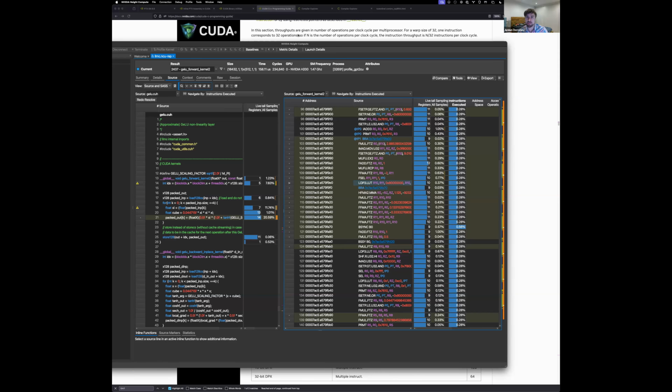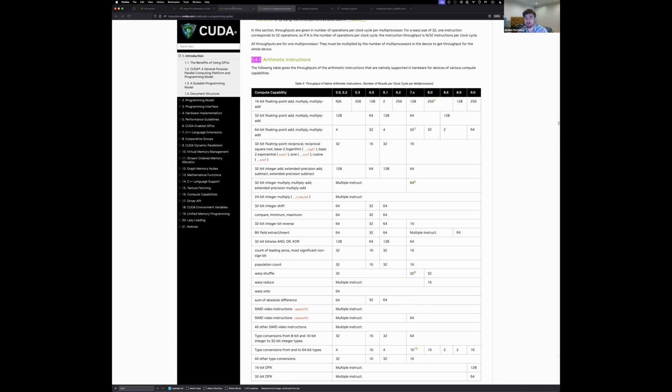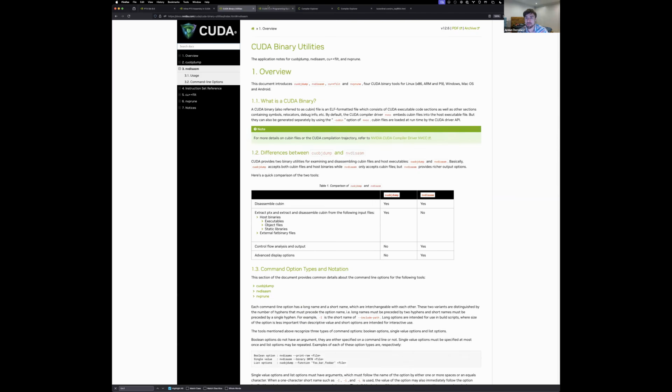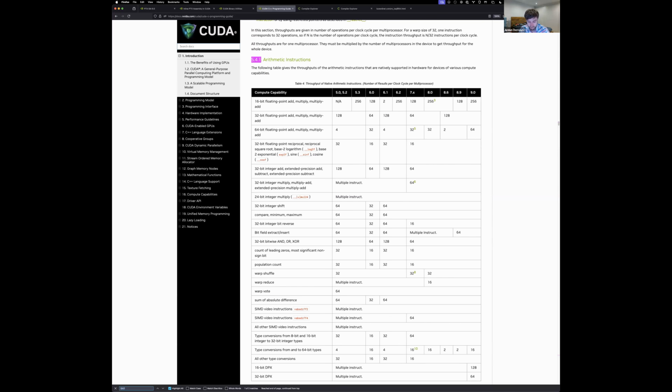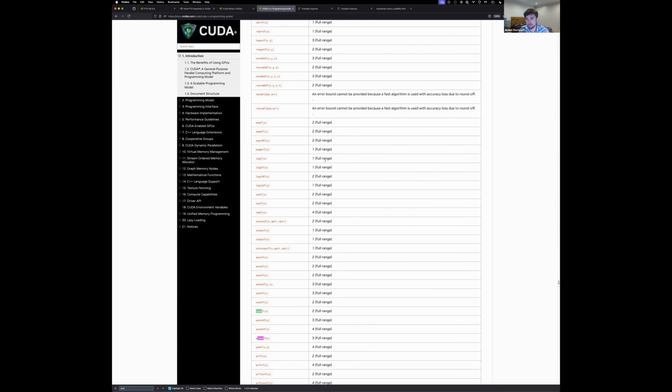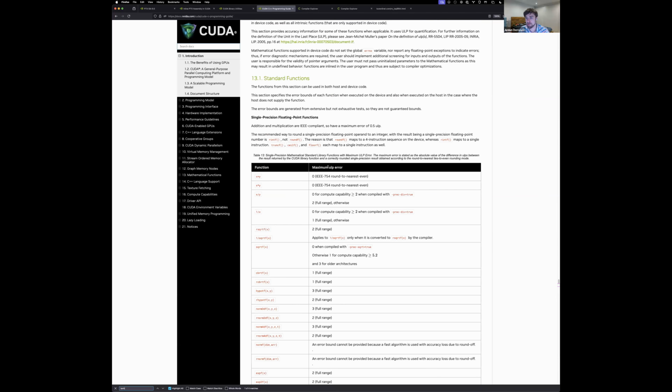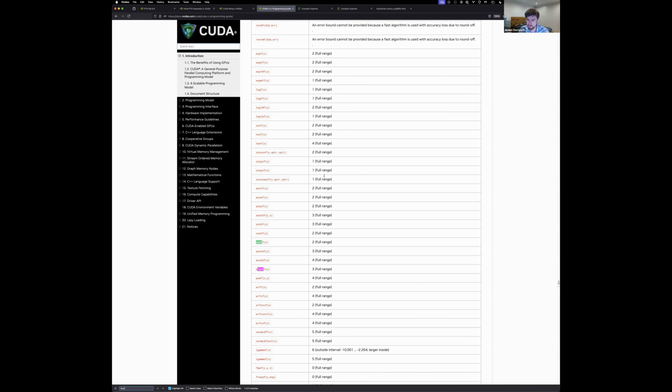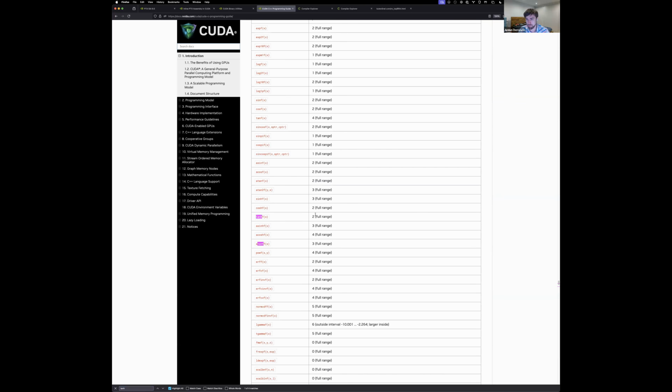The reason is that if you look at the CUDA specification, for tanh there's a very specific precision requirement, which might actually be defined by IEEE 754, I'm not entirely sure: it has to be 2 ULP error maximum over the entire range. It's really tricky both in hardware and software to get that performance across the entire range.